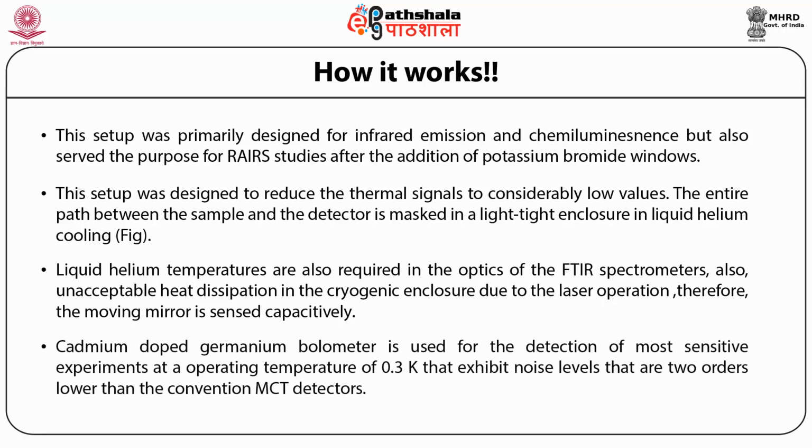A cadmium doped germanium bolometer is used for the detection in the most sensitive experiments at an operating temperature of 0.3 degrees Kelvin. It exhibits noise levels that are 2 orders lower than the conventional MCT detectors, which have been used earlier.